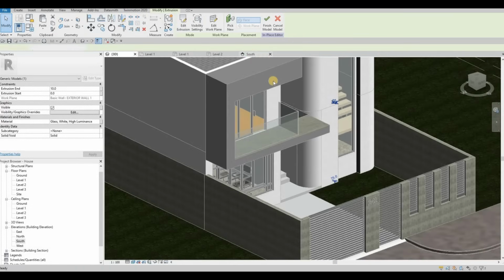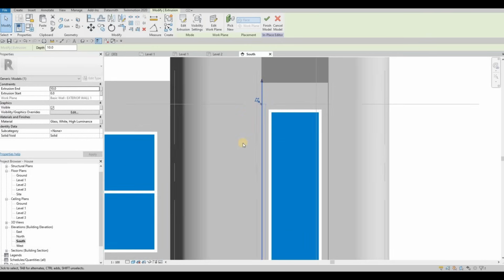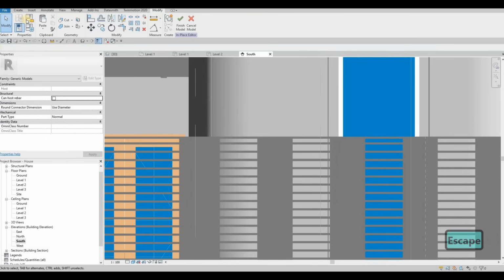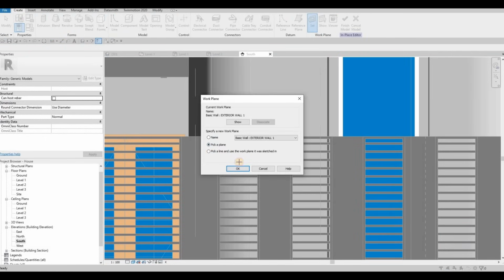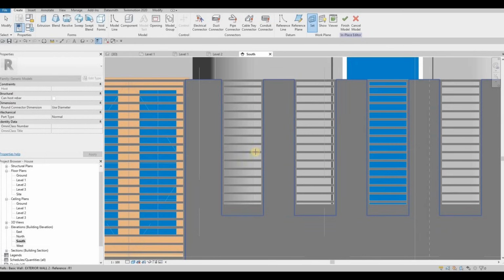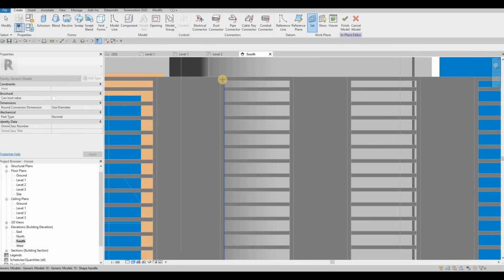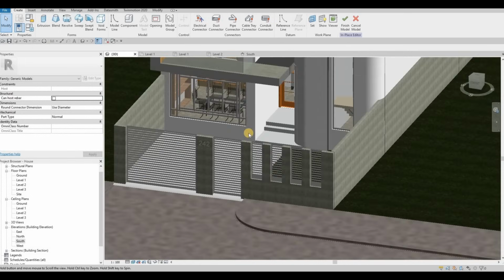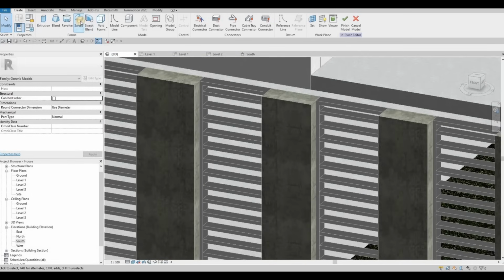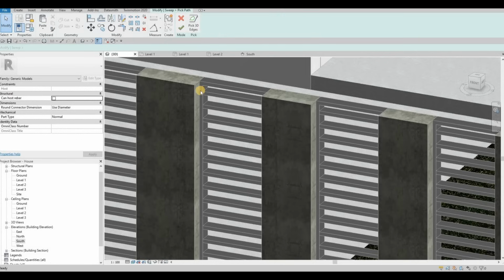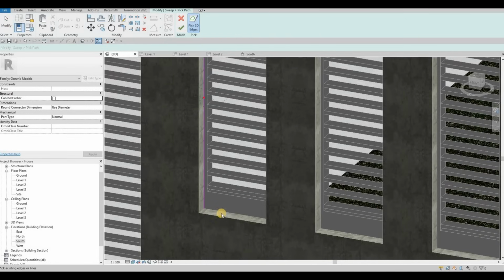and then once we're still here in the edit extrusion, we could now set this one to a different plane. So add another plane, and we could add it onto this metal right here. Once that's selected, we can go 3D, and then we could do a sweep now. So pick path. I'm gonna select this path right here.